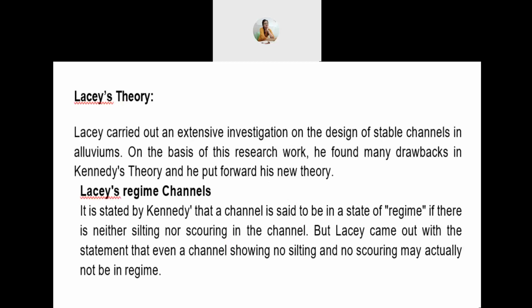Next, Lacey's theory. Lacey carried out an extensive investigation on the design of stable channels in alluvium. On the basis of this research work, he found many drawbacks in Kennedy's theory and he put forward his new theory. In Lacey's regime channels, it is stated by Kennedy that a channel is said to be in a state of regime if there is neither silting nor scouring in the channel. But Lacey came out with a statement that even a channel showing no silting and no scouring may actually not be in regime.